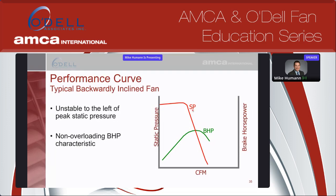Show some characteristics of the fan curves. So here's our fan static curve. So again, you kind of have this zone up here that we don't want to operate. You have your peak pressure. So really, you're going to be typically operating your curve here for these types of fans on a backward incline, because we're unstable up in this region, because any variation in pressure is a large swing in flow.